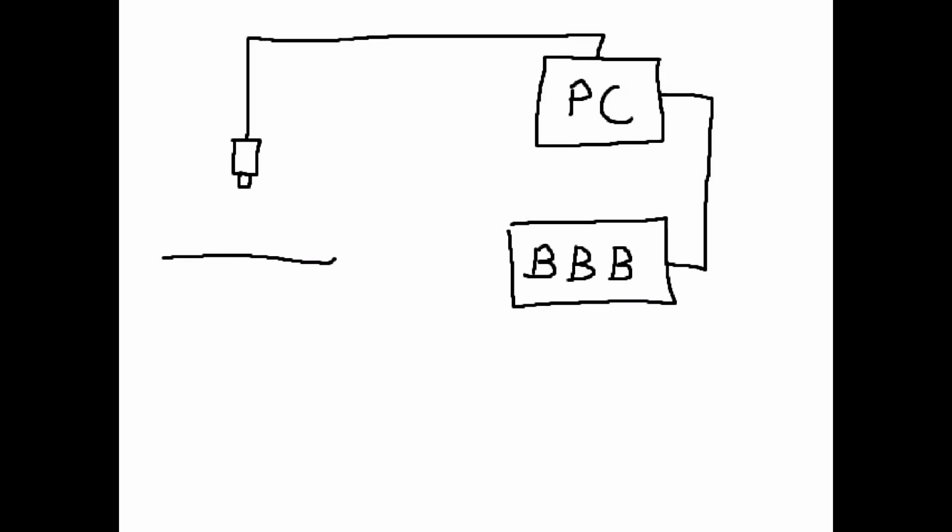The action and behavior modules, as currently implemented, are not terribly sophisticated. However, they are intended to act as replaceable units which can be substituted in as required in order to generate specific behaviors. The inputs and outputs of a behavior module are standardized so they can easily be swapped in for one another. The output is an integer number between 0 and 99, which represents a proportion of the speed between min and max, and a Boolean value of 0 or 1, which represents a direction. Once the action module gets the output from the behavior module, it can send signals to the motor drivers.